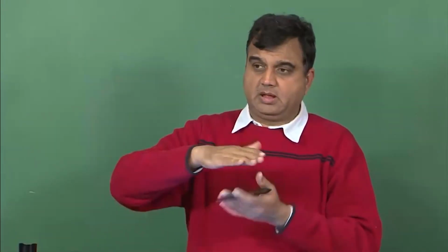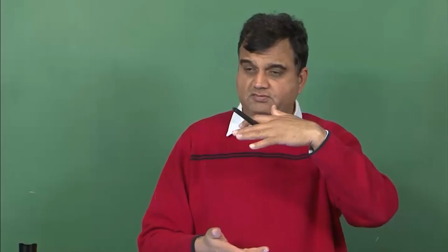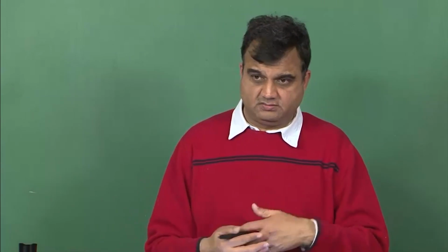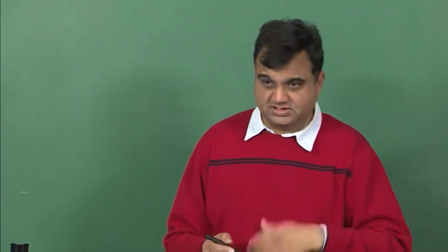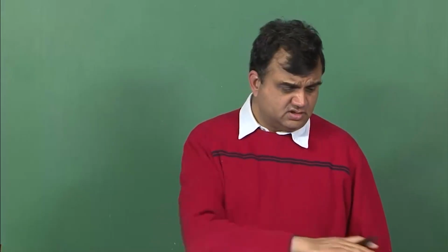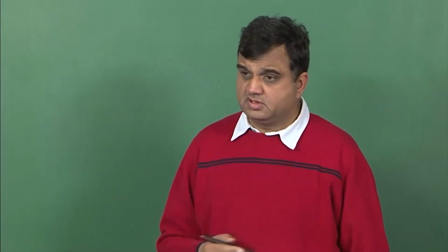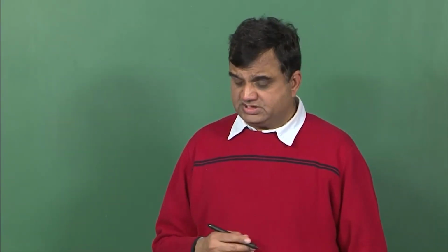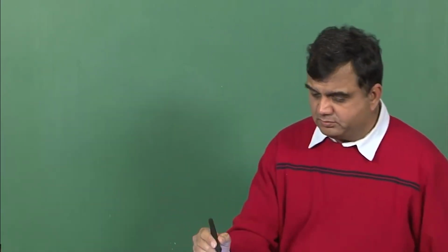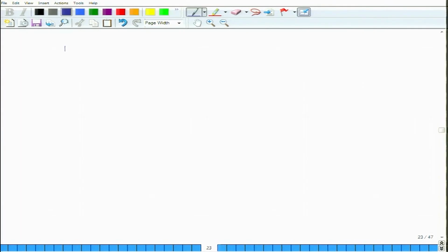We can stack them upon each other in the orientation we want, and again when we apply heat and pressure they fuse and we can make a layered structure from this. So, this is the third process. So, this is what I wanted to discuss in context of thermoplastic based composite materials. Next, for the next 5-10 minutes we will discuss metal matrix composites.